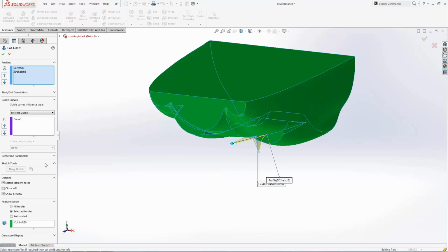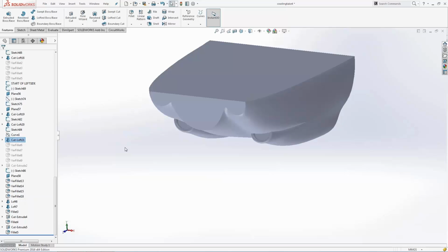Right, so one of the things that I point out here is these merge options. Whenever you're extruding, this was a loft, but if you do an extrusion, anytime I extrude these things, I have the availability as the modeler to tell this program how I want it to handle that data. So by merging data, it's going to tell it that this is all one solid. This is kind of cut out of one piece of metal. So many of the functions that I used here, one of the key steps was to uncheck these merge options. And again, they'll vary in your dialogue, but just to understand what they do.